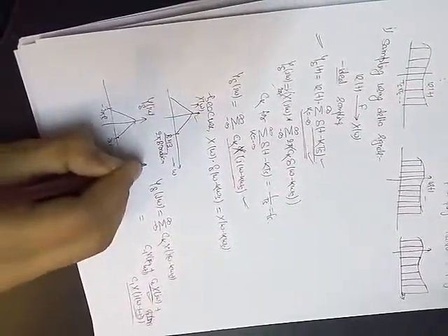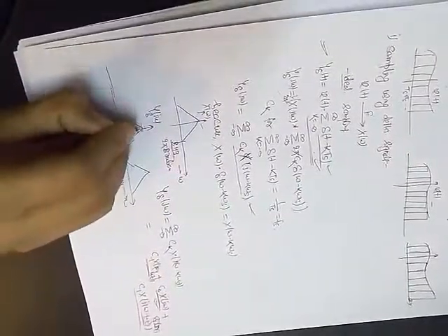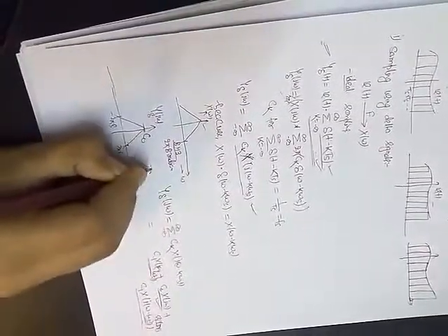So its diagram will be something like this: the same X(ω) at baseband, from −2πB to 2πB, and its shifted version, shifted by an amount ωs. It will be scaled by c0, and this will be scaled by c1.